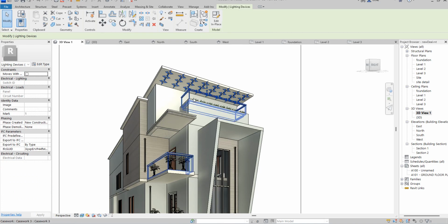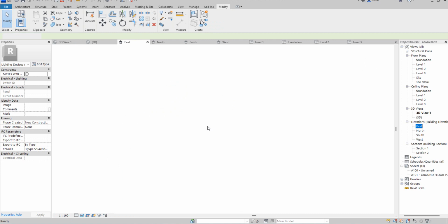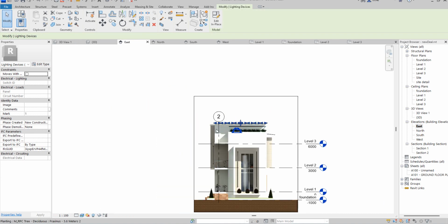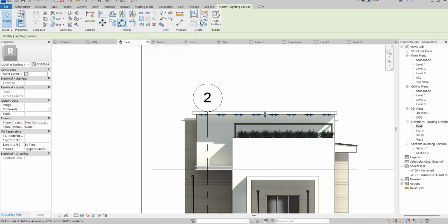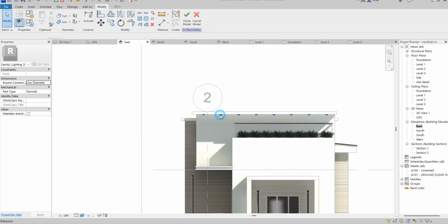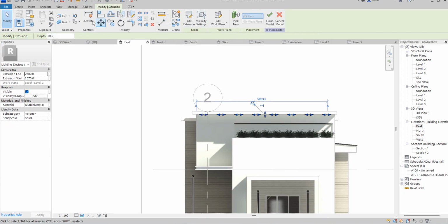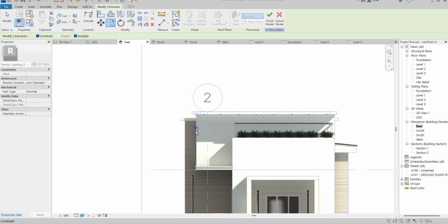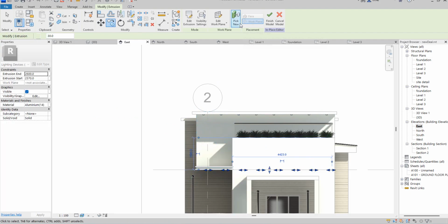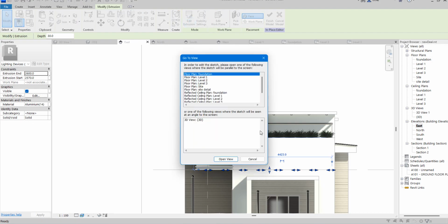So what you do is just that you select like that, go to start elevation, front elevation. From there now you use the same thing. So here you just say copy, or you edit extrusion because they are the same family member. So you edit like that and you say copy. From this pair, you say copy. From the copy, you remove it from constraint and you drop it in. So in the extrusion aspect, that is where you are going to edit them.